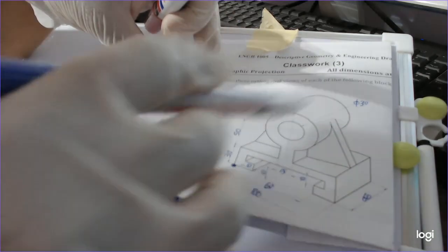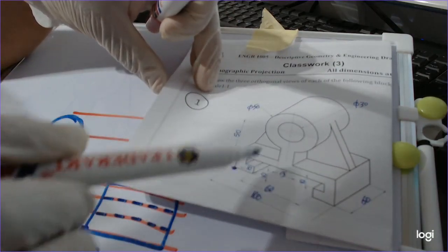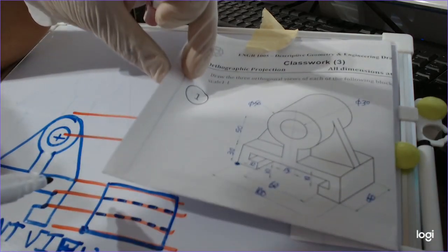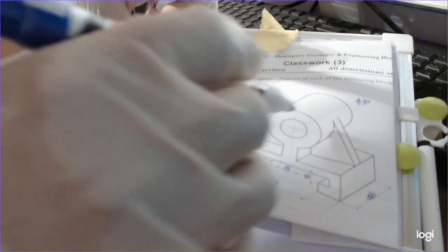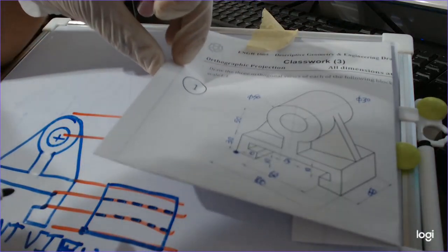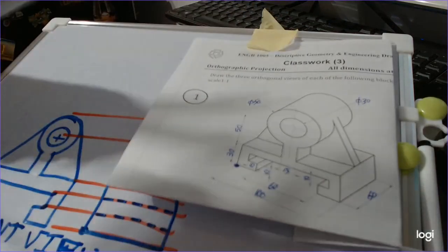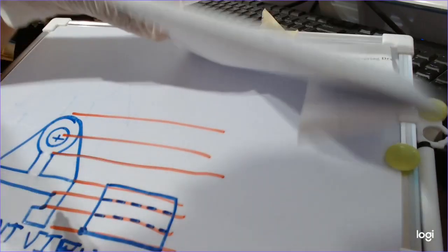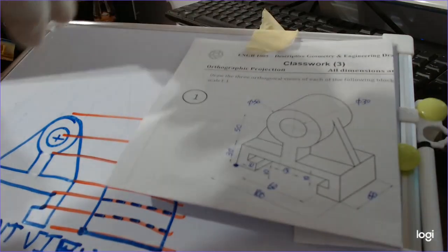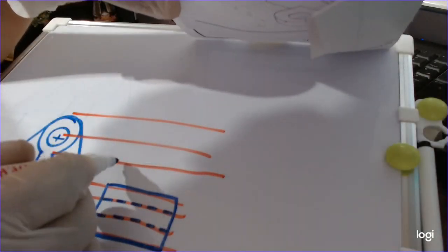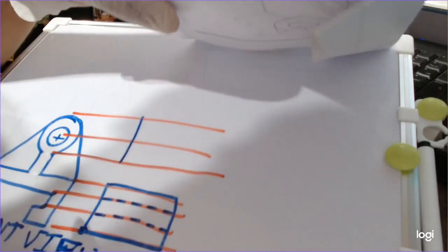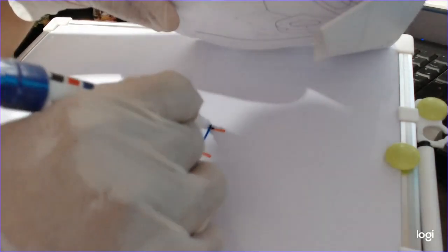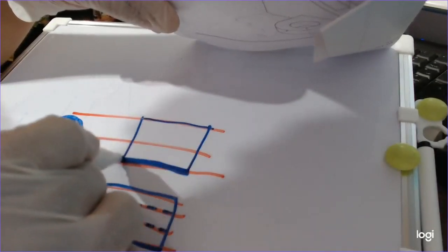if we look at this cylinder, it starts from the first face and ends with the back face. So the width or the depth of this cylinder will be 60. Okay, so we'll take projection line from that point. Okay, so now we know the start point of the cylinder, which will be that point. Go up until this point, go 60. We have something like that.